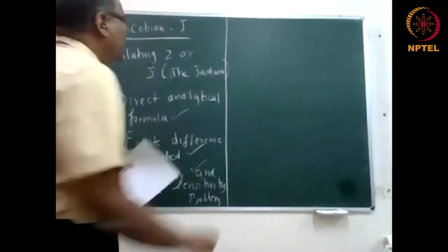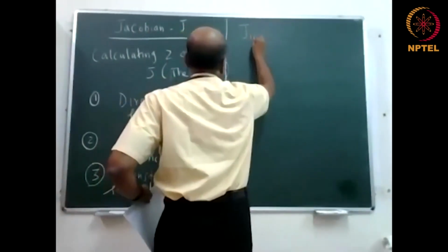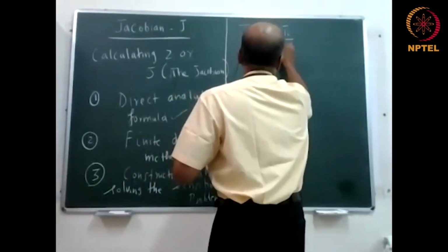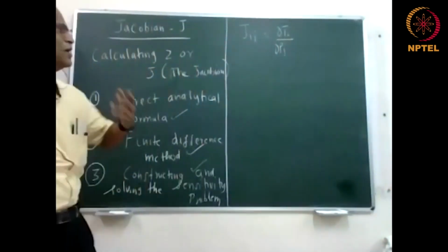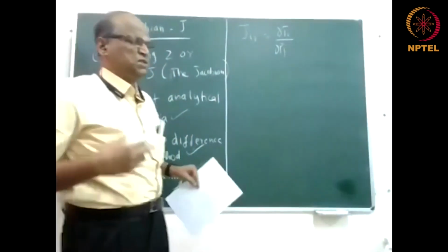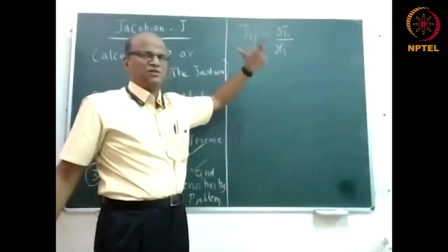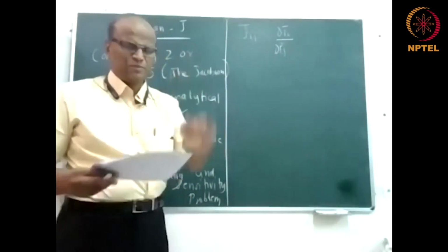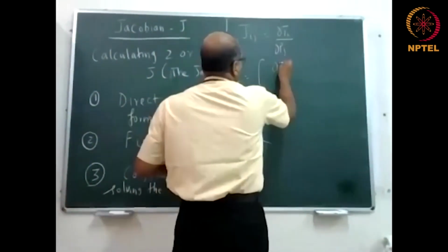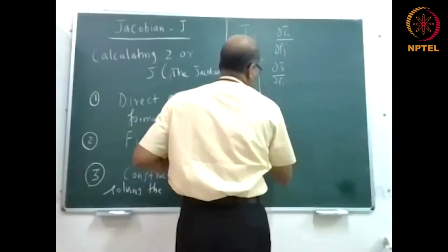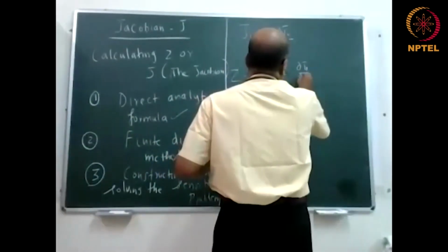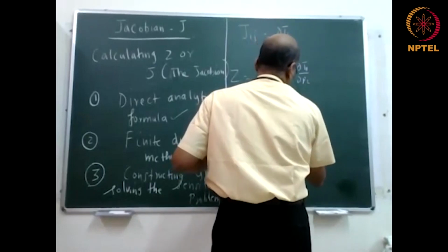Now, Jij equal to dou Ti by dou Pj, for example. Let's say temperature is a function of a parameter. P is usually used for parameter. That parameter can be thermal conductivity, density, specific heat, emissivity, or whatever. In this case, it could be the time constant, A, B, whatever. The parameter is generally denoted as P and temperature is T. So the Z is dou T1 by dou P1, dou Tn by dou P1, dou T1 by dou P2, dou Tn by dou P2.